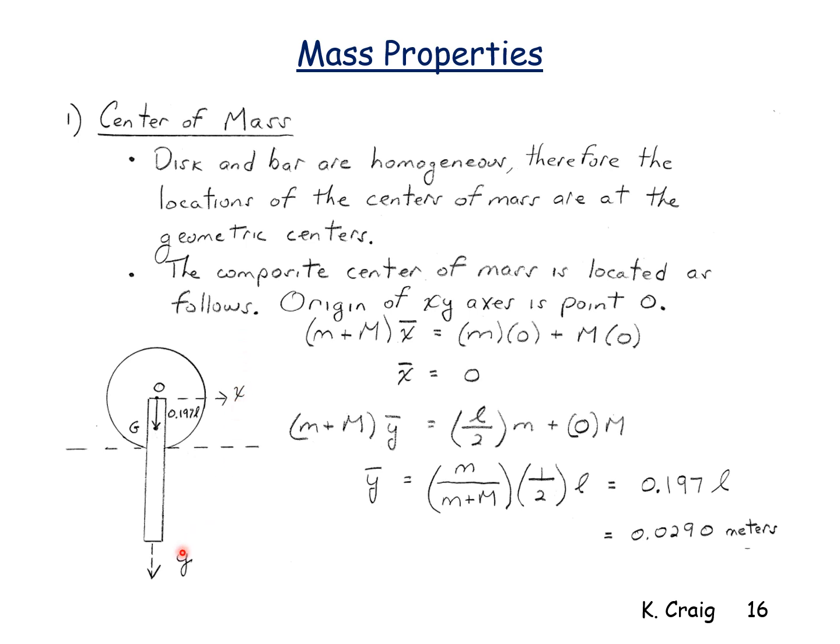Using my X and Y coordinate system with an origin at point O, with the X-axis to the right and the Y-axis vertical, I know that the center of mass by symmetry has to be located on the Y-axis because I have the same amount of mass on the YZ plane to the positive X direction as I do from the YZ plane in the negative X direction. I have mass symmetry.